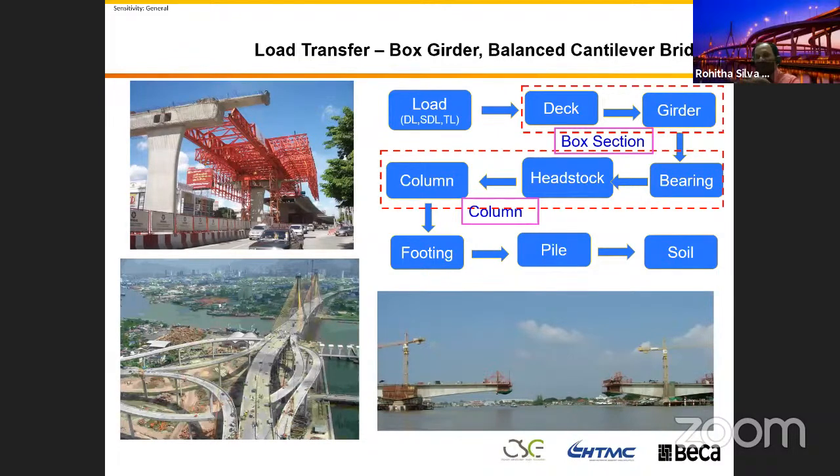Yeah, because of these bridges, we need the flexibility of the bridge, because you will see in the articulation, we need the flexibility of the bridge. You can see the length of the bridge, 660. The bridge is subjected to creep and shrinkage and thermal expansion and contraction, as a massive force. That load needs to be absorbed.